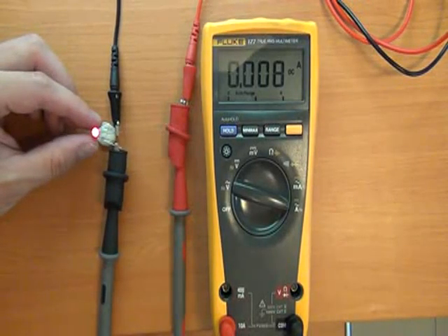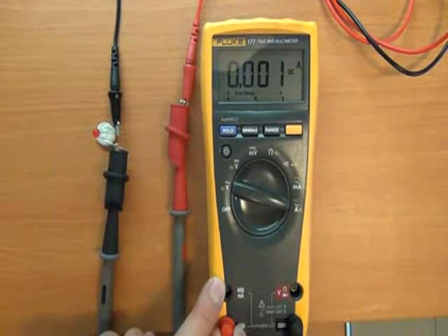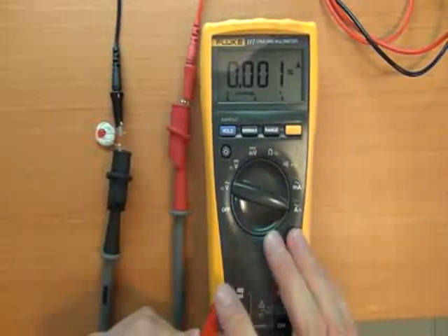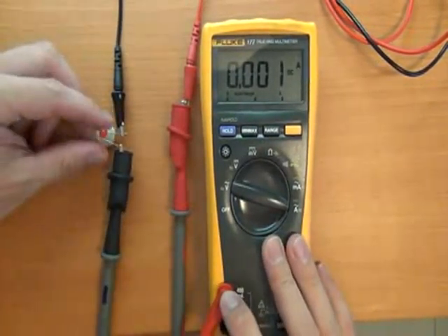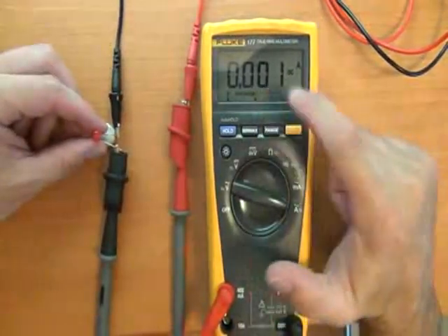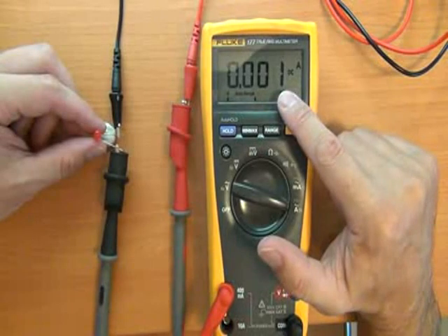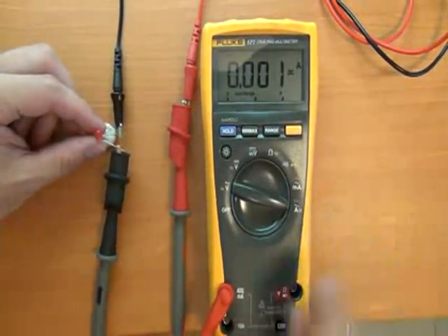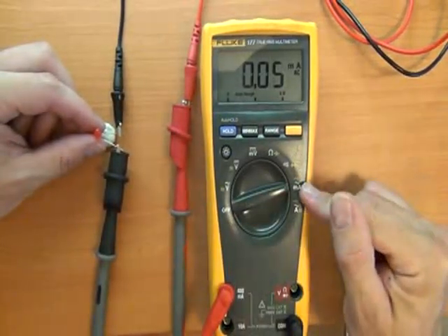So now we can go and change things over. I'm going to switch off the power supply. I'm going to simply change the red connection point to the 400 milliamp. Okay. As we saw, 400 milliamp, it wasn't near 400 milliamp on the multimeter. We can now go to the milliamp setting on this Fluke 177. So I've switched it over.